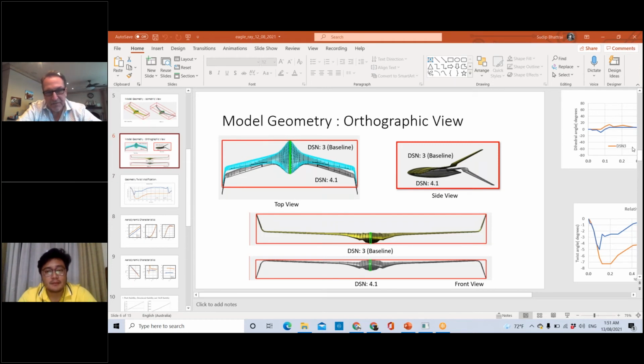So another point about the winglets, Mark, was initially we were instructed by Ron to place the landing gear exactly at the tip of the winglets. Handling wise, for some reason, I can't tell whether it's an X-Plane thing, but I could not really maintain a good ground run when I had a tiny winglet at the wingtips.